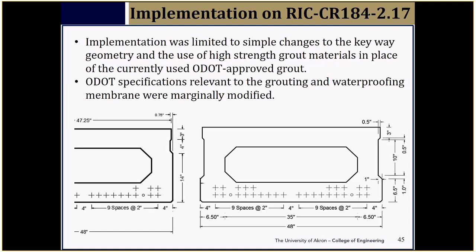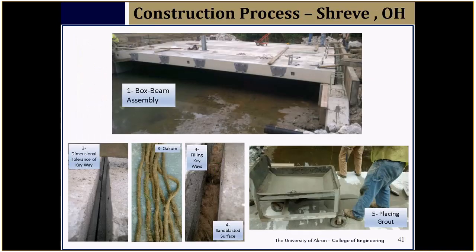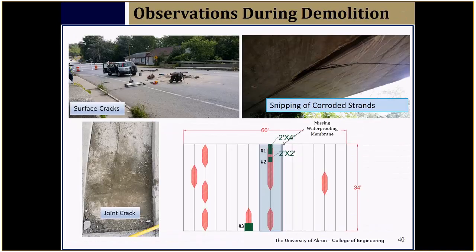So you went to a bridge that had been in service for 20, 25 years, and they were removing the beams because the beams were pretty much shot. The intent was that the contractor would remove the wearing surface carefully so that you could then examine and remove the membrane that had been placed.